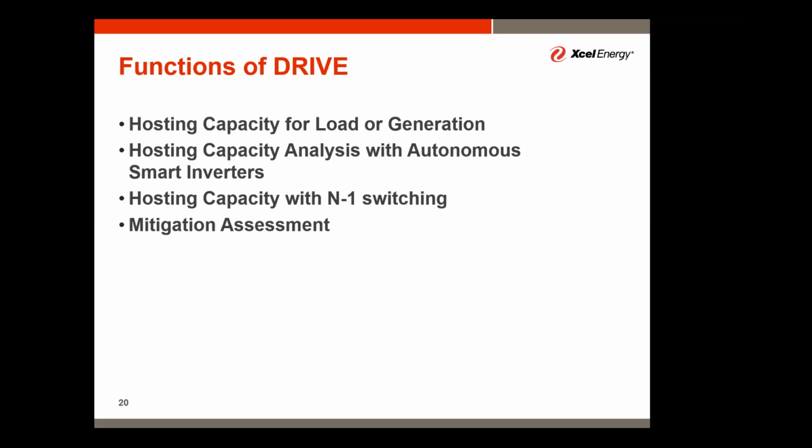And I'd like to reiterate that that is a very location-based assessment. It does not work the same way that the hosting capacity analysis performs, where you can input an entire feeder or even an entire substation and have those values calculated. The mitigation assessment requires a specific point on those feeders to say we are increasing the hosting capacity from, again, point X to point Y, with Y being higher.